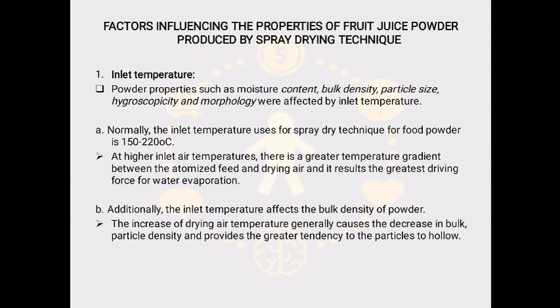At higher inlet air temperature, there is a greater temperature gradient between the atomized feed and the drying air, and it results in the greatest driving force for water evaporation. Additionally, the inlet temperature affects the bulk density of the powder. An increase of drying air temperature generally causes a decrease in bulk particle density and gives the particles a greater tendency to become hollow.